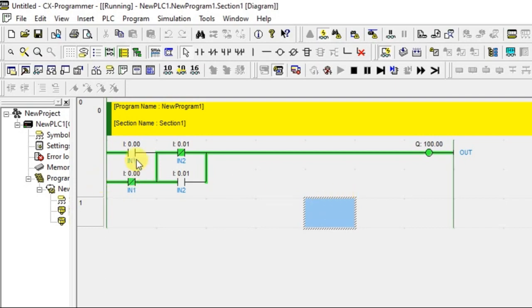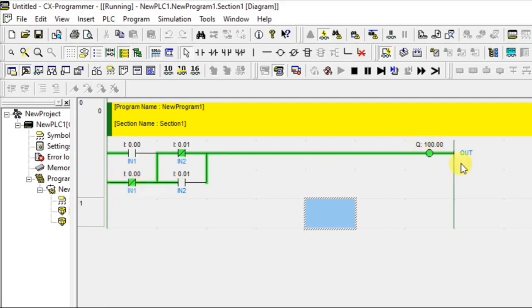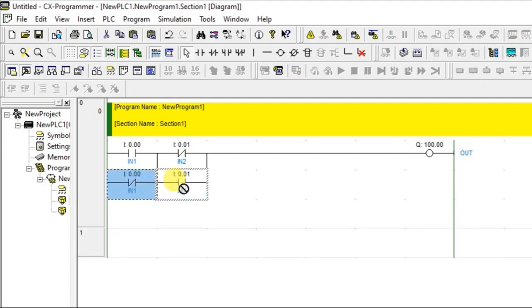Okay. Now the input is coming from this location. See how the output is on? From here it is going through this location. The route it is taking: the power from the positive rail is passing through the normally closed contact I 0.0 and the normally closed contact of I 0.01. So my output has to be in off condition, no? So the order of putting the contacts is wrong here. So what I have to do is, instead of putting this here, I'm putting it there.